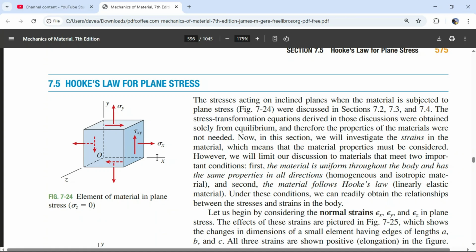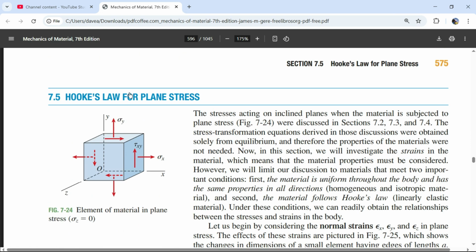Just like up here, if we had a 1-inch steel bar, we could put a max pressure in the normal direction. We could have a normal stress up to 58,000. But let's say we're just pulling half that on that same area. Well, this number, our given number, is going to be half. But for what we're doing in this chapter, we found these numbers fairly easily, because this is just the unrotated direction. And we can find all three of these numbers.